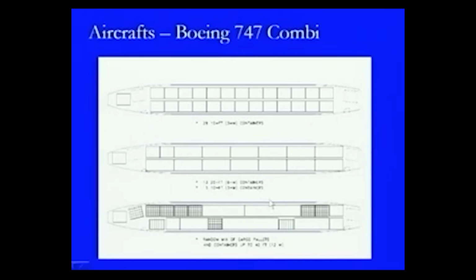This is regarding the 747 Combi, where it can take the passengers as well as the freight or the cargo, and there can be different ways in which the cargo can be placed. All these three diagrams are trying to show the cargo condition only, where these are the smaller boxes of 10 feet or 3 meters dimensions. So, how many can come in this one, and then if it is a 20 feet and a 10 feet combination, then this is how this can be adjusted, whereas at times there can be bigger containers also, like shown this way or this way, and then these are being merged, and this is a mixed condition in this one, where smaller, medium and the bigger containers have been used.